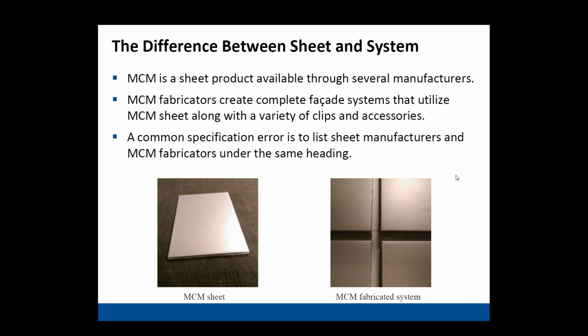One thing you really need to do is avoid over-specifying, and finding yourself with situations where there are elements in your spec that are proprietary to one fabricator or another. Again, going back to that spec section that was provided by Zeke is a good place to start. Next slide, please.